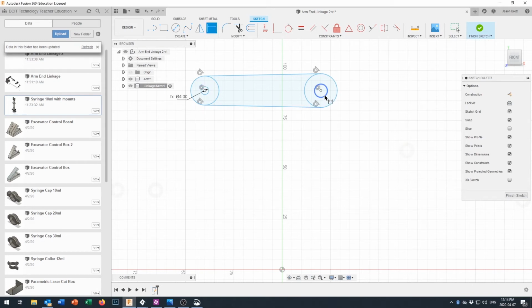And this one right here is going to be hole inside diameter. Now, the reason I'm using hole ID as a parameter instead of just using 4 everywhere is maybe as we assemble this, we find it's a bit floppy and we want to change from a number 6 screw to a number 8 screw or something like that. And if we do, then we just change that one parameter and everything in our drawing immediately changes.